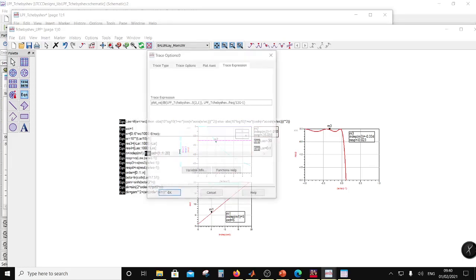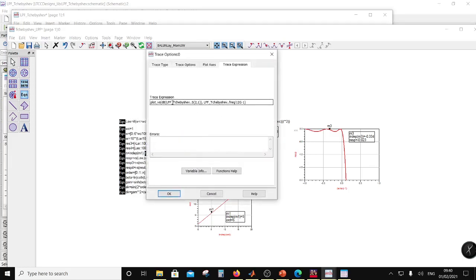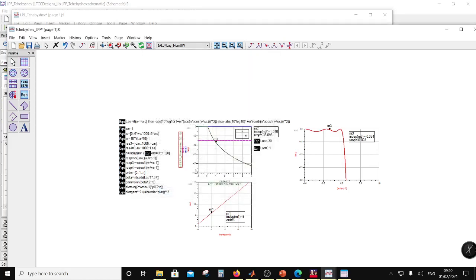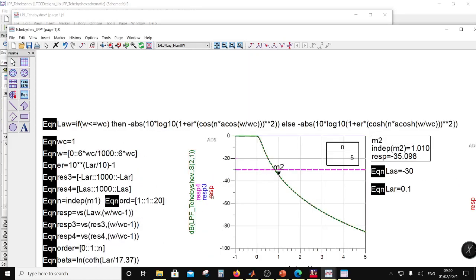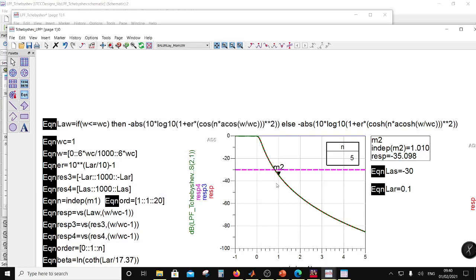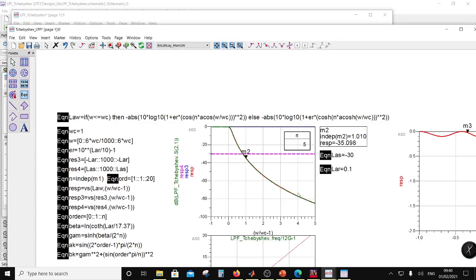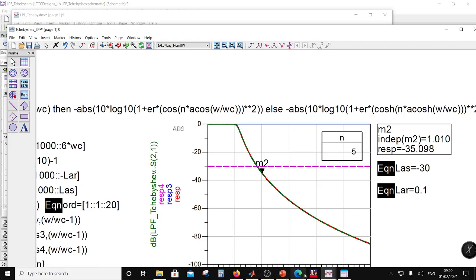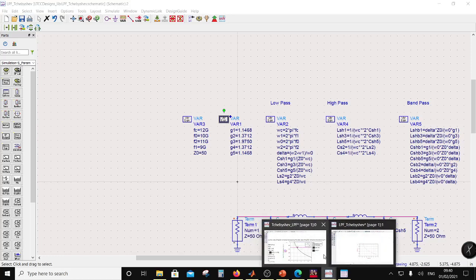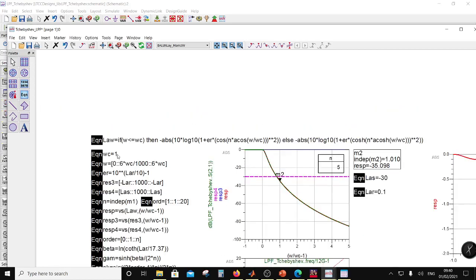And you will see that again this is on top of that. So let me just change the color to be green, and let's do a dotted line. Okay, so what does it look like? It looks like the polynomial and its fifth order approximation are almost the same, right? So the green one is coming from this circuit simulation for Chebyshev, isn't it? And that red one is coming from the equation. This is the equation for a Chebyshev polynomial, right?